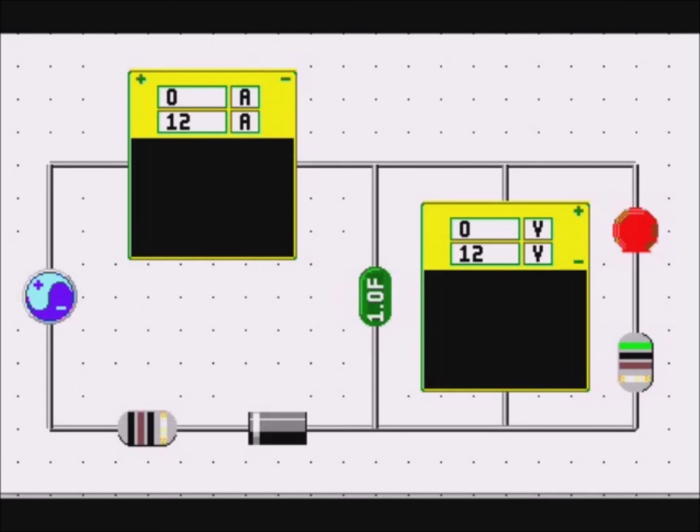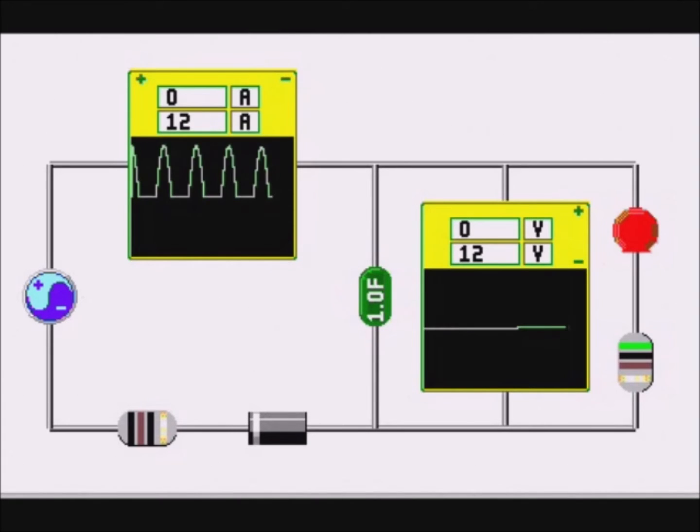Consider this circuit. Because the diode only allows current to flow in one direction, the voltage of the capacitor builds up. Here the simulator is running at 1/10 speed. We see that the capacitor becomes like a battery and in due course is able to provide direct current to the LED. Notice that we are losing half the energy from our generator as no charge is accumulated from the downward half cycle of the input wave. This will be solved by the full wave bridge rectifier.